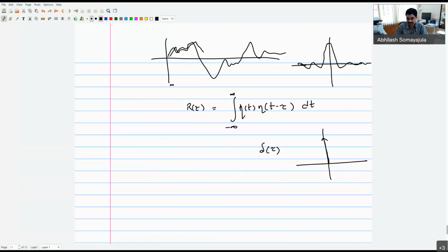So the white noise will be like itself only at zero, like tau is equal to zero. No, no, no. This does not mean that the signal will be zero at every time. Like you are saying the autocorrelation, right? It will be correlated to itself only at that time step. At the very next time step, it can be anywhere.